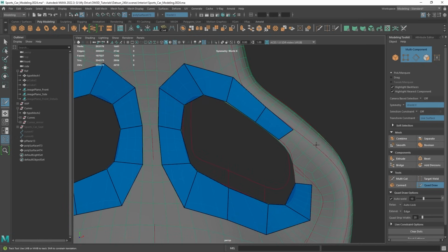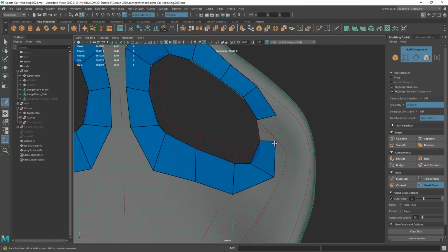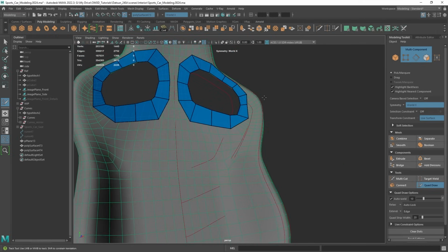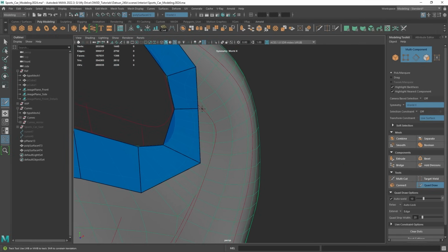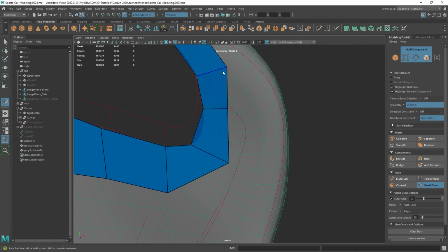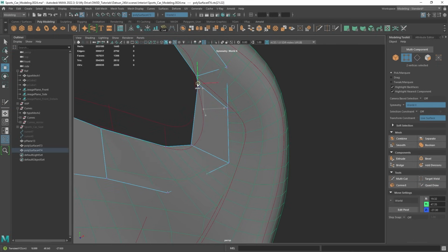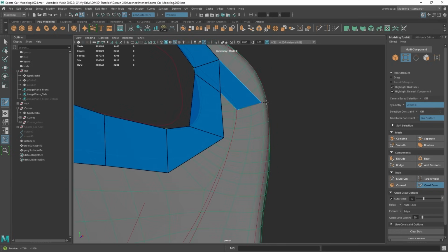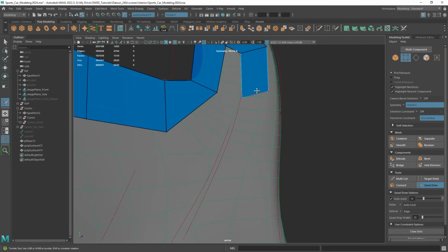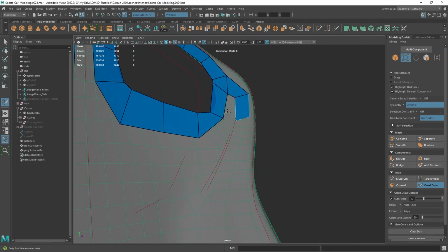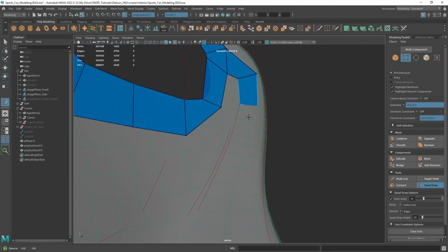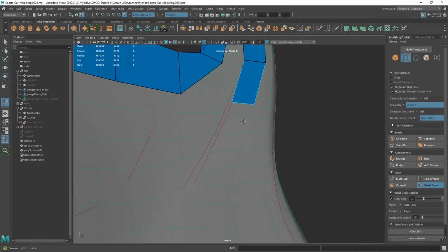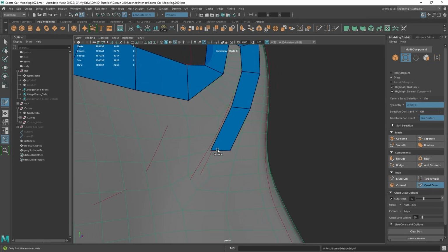Just like if you're modeling facial topology, you focus on the loops first, and then from there you go through the process of creating the details. So I can now go to Quad Draw, and you can also hold Tab and left click, and you can start to see, all right, cool. Now I can start to drag this and create more complex flow. You can see this red line, hopefully that's coming through in the recording, and I can drag this and follow this red line, which is the curve guides.